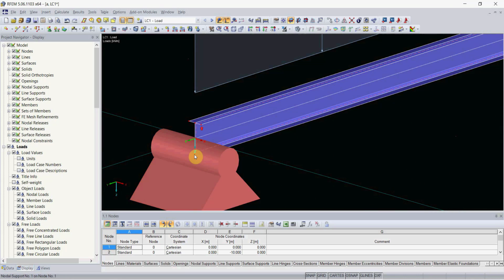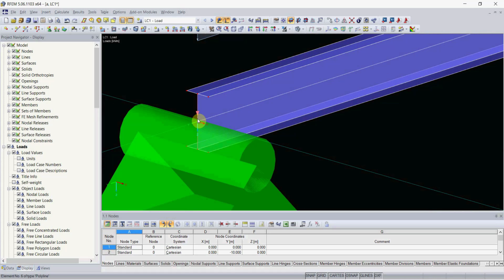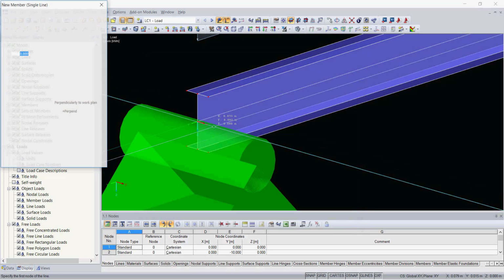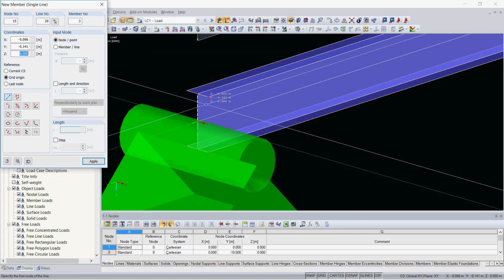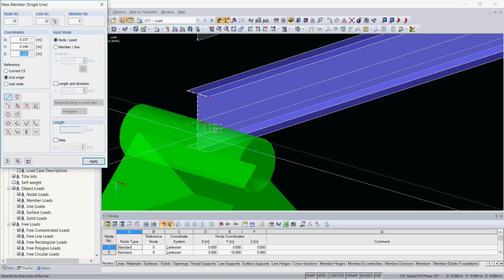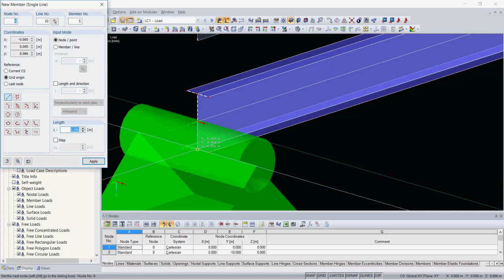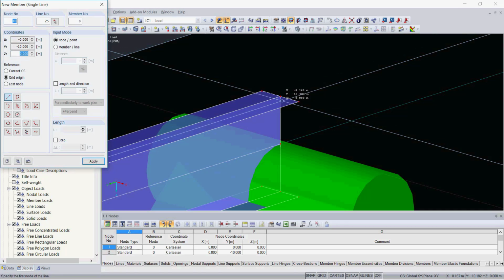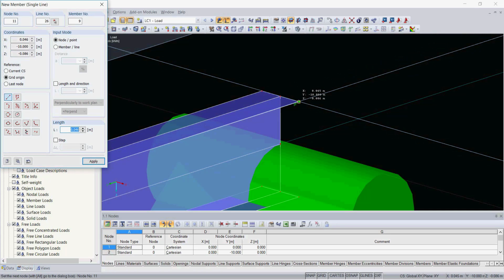Also, since we are using plate elements, now the support in this point only supports a very tiny fraction of the cross-section. This will of course cause significant stress concentration, so in order to avoid that, I will use rigid beams at the end, simply to allow better stress distribution. This of course does not change the fact that the support is still a hinge.